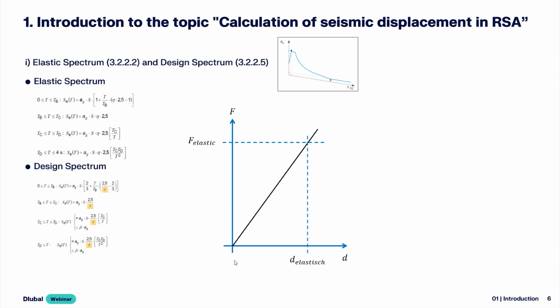The black line represents the elastic response of the structure, and that's the assumption of this kind of analysis. RSA is a linear analysis, and we can perform this analysis represented with this line. Now we know that in reality the structure is going to exhibit some degree of inelasticity. The difference between the forces can be summarized as this behavior factor mathematically, but physically it has an interpretation.